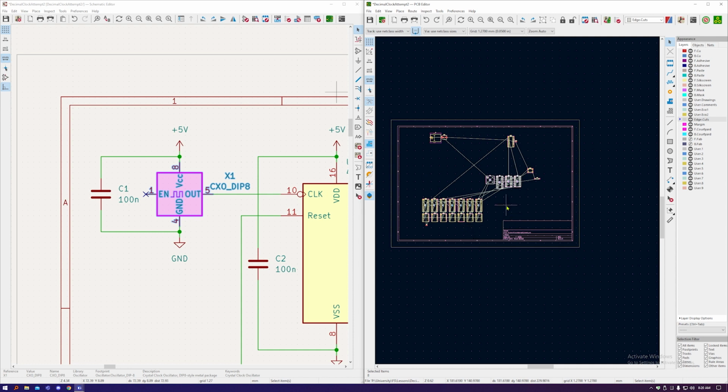And in that case, I would recommend making it 10 by 10 centimeters square, because unfortunately I'm not paid to say this yet, but I would recommend JLCPCB. The minimum quantity of PCBs you can order is 5, and if you're ordering 5 PCBs, the price is the same up to 10 by 10 centimeters, or technically 4 by 4 inches. That's why I'd recommend that size. You don't save any money by going smaller, just for a test board.